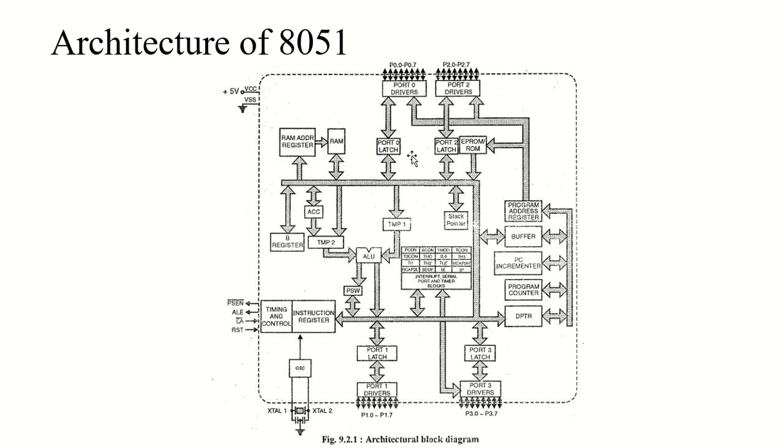Then we have the serial data input output. For communication between two computer systems, we need to send and receive the data serially. The 8051 microcontroller has a serial data communication circuit, which uses a register in the SFR called SBUF to hold the data, the register SCON controls the data communication, and the register PCON controls the data rates.